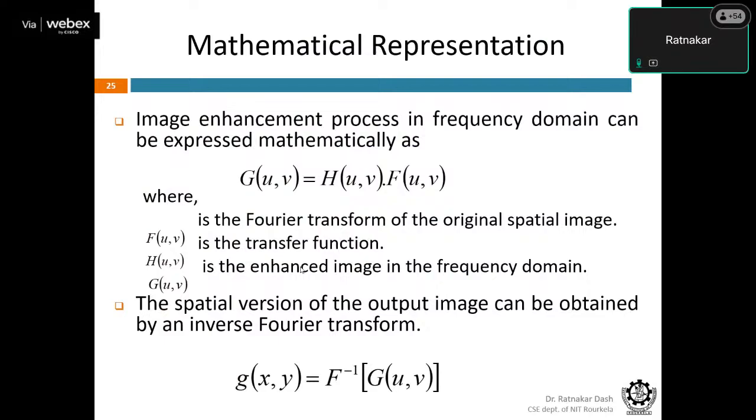In order to get filtering for a particular image or signal, we need to apply the convolution operation of the particular mask onto the image. Instead of applying the mask onto the whole image, convolution is done on a window by window basis. We take the mask on a window, on a particular area of the image, and try to get the features out of that. That is the same as the convolution operation.